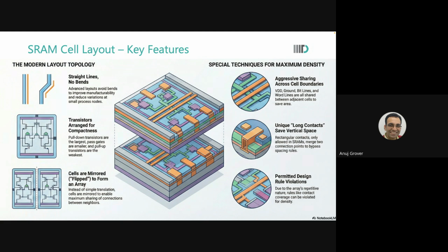There is also another DRC violation on the spacing between the actives and the n-well. So you do whatever you can, because it's a very systematic structure and because you know that you are anyways going to characterize the particular cell, each device in the particular cell separately. So you go ahead and do many violations there.